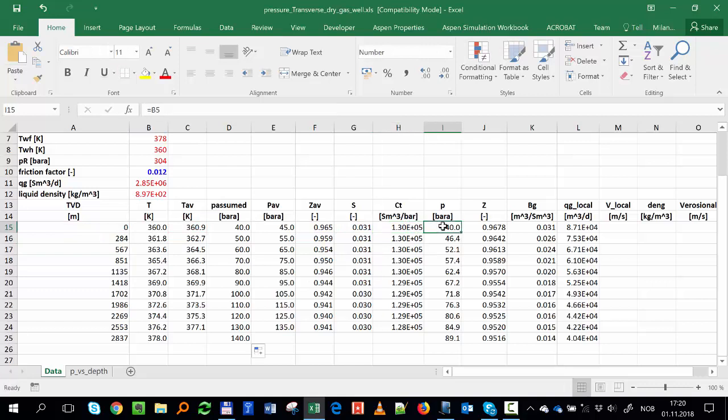And then we start from the point where we know the pressure, which is the wellhead. We have pressure at the wellhead. We find the pressure at the inlet of the first segment, then the pressure at the inlet of the second segment. It doesn't work if you start the other way, because you don't have the bottom hole pressure. So you have to start from the top. I have P2, I calculate P1. Then I have my new P2. Now I have P2, I want to calculate P1 sequentially.